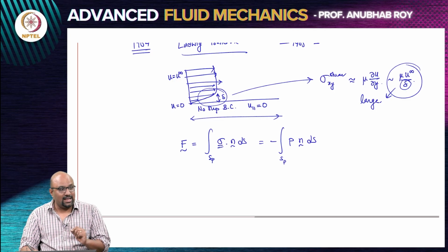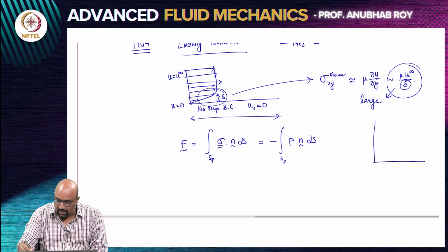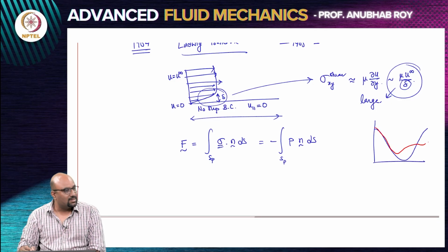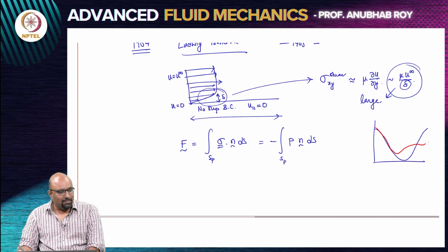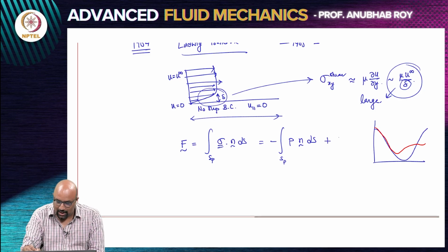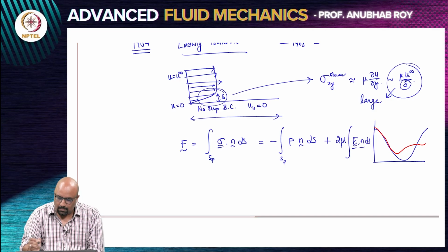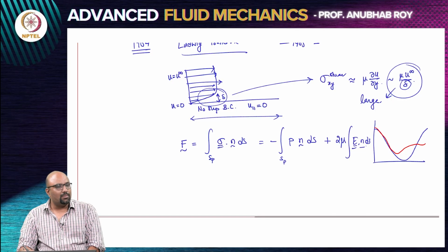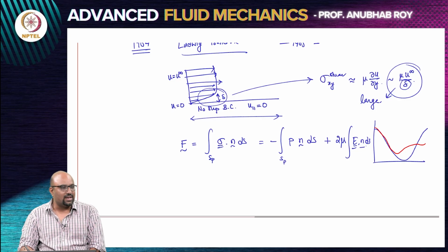So yes, you can say that the modification of pressure, if you go back to the picture that I was drawing of Cp, will look something like this. Yes, that modification of pressure is going to modify the force. But there is also one part which is missing here, that is the contribution from the viscous stress or the shear stress. There will be a shear stress contribution in the force calculation.